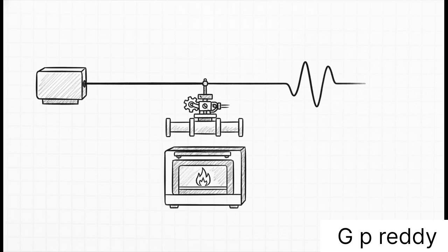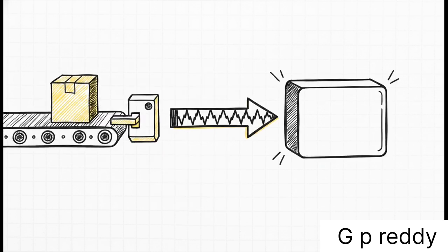You'll also see AOs used to send speed commands to a VFD, that's a variable frequency drive, smoothly spinning a motor up or down rather than just aggressively jerking it on and off. Okay, let's shift gears to the digital side of things and see how this fills out our vocabulary. A digital input, or DI, is entirely different from its analog cousin. This is a snappy, definitive on or off signal coming into the controller.